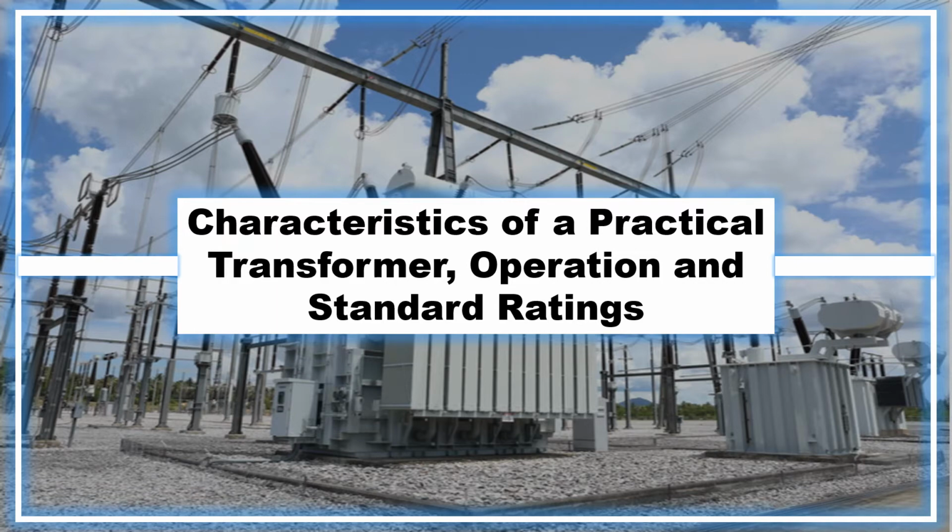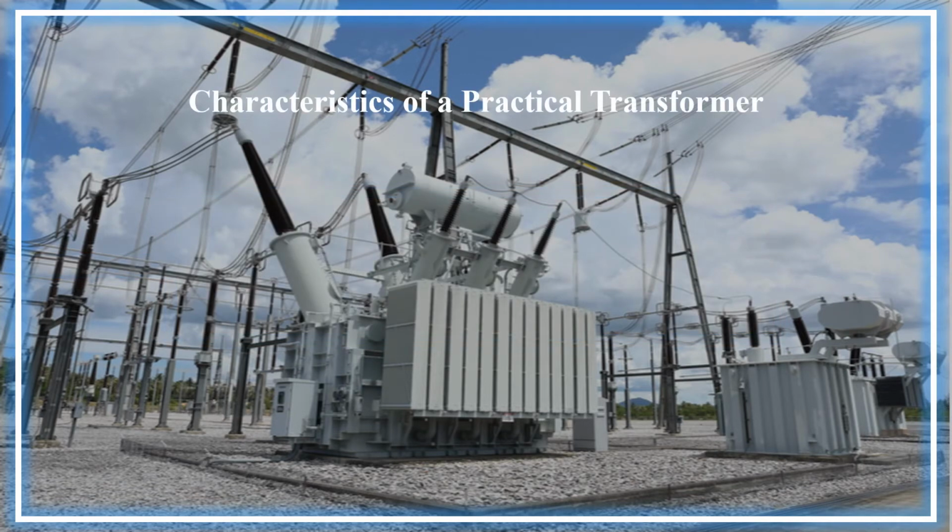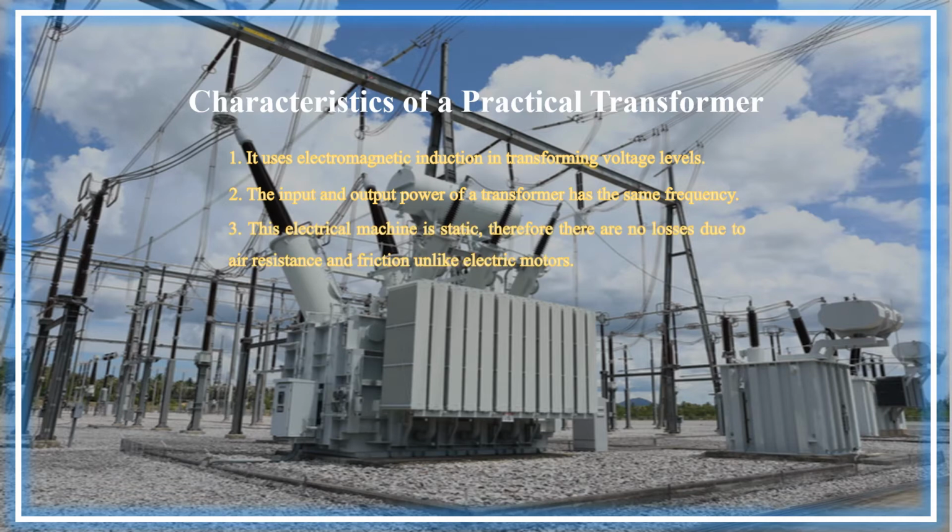So, without further ado, let's begin with the characteristics of practical transformer. First, it uses electromagnetic induction in transforming voltage levels. Second, the input and output power of a transformer has the same frequency. Third, the electrical machine is static, therefore there are no losses due to air resistance and friction, unlike electric motors. Fourth, it has copper losses since the windings are electrical wire with resistance no matter how small. And lastly, it has core losses due to eddy currents and hysteresis losses.